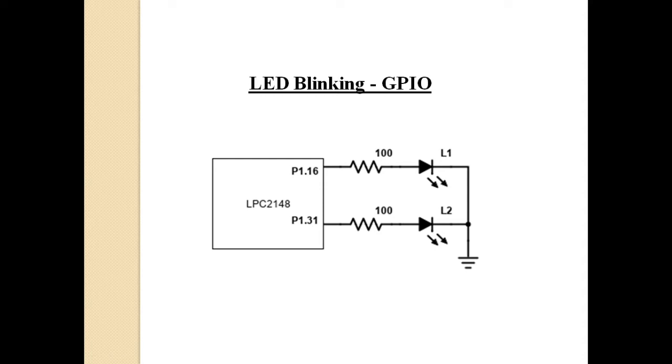Now we are going to do the first experiment with LPC2148. The first experiment will be blinking of some LEDs connected to GPIO port. So here I have connected 16 LEDs from P1.16, that is the 16th pin of port 1, till the 31st pin of port 1, P1.31.